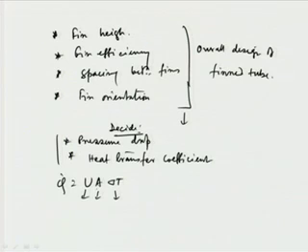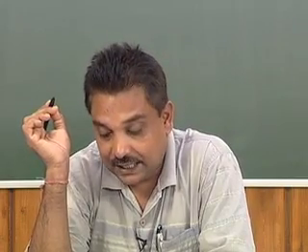And therefore the rate of heat transfer becomes less, because if you see, the rate of heat transfer depends upon the area, U and delta T. Delta T, as I told previously also, cannot be independent, it is decided by the external world, and for U there is a maximum value that can be obtained by changing the flow rate. So, even by making a very high flow you can obtain only some maximum amount of U, and also there are flow rate limitations, the cost of pumping or the cost of the compressor, all these things have to be taken into consideration, and then what stays in our hand is the area.